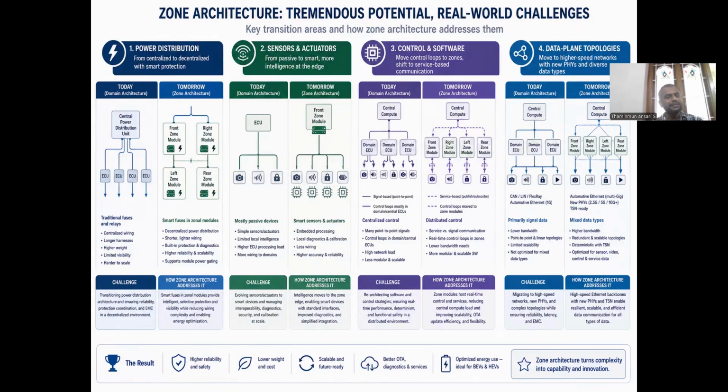But here, sometimes they use some sort of switches to reset it. Sometimes they use software to reset that fuse. That much flexibility is what we have in smart switches. In zone architecture, they use these transistor-based fuses to control the overcurrent, and the impact created by an overcurrent or short circuit.